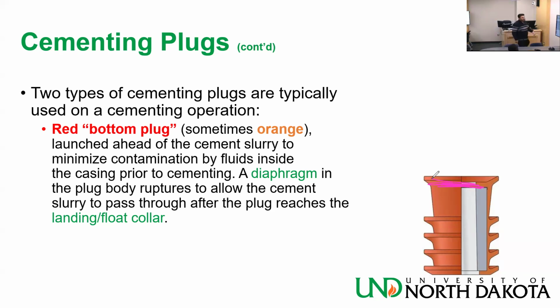If it touches the float collar, it stops. Then you keep pumping, and it raises the pressure above it. You apply more and more pressure, and then this ruptures, and then cement can flow through. It will rupture intentionally, basically. This is the bottom plug.